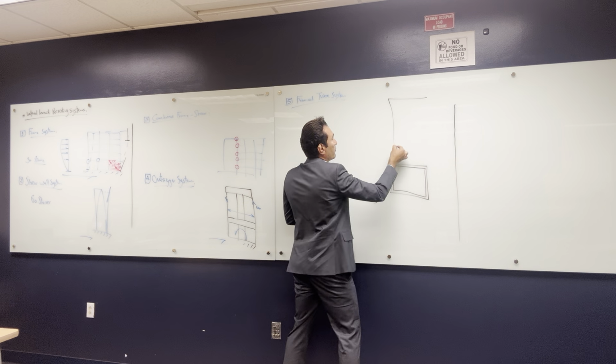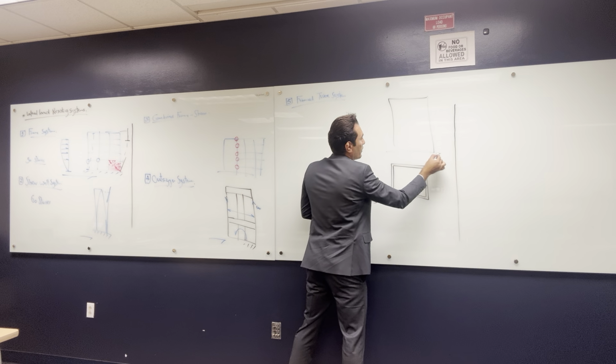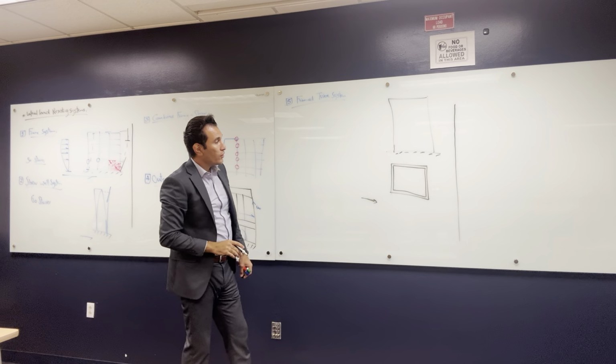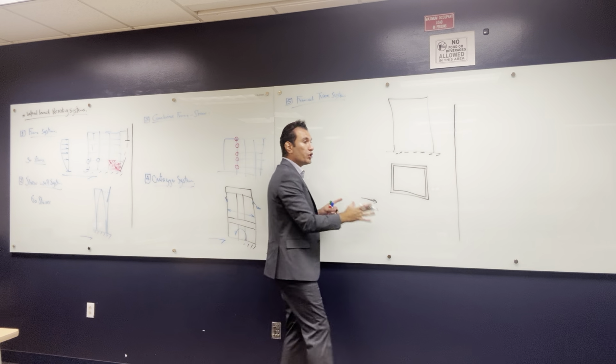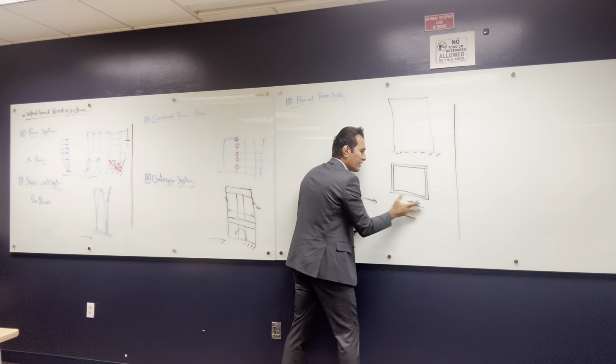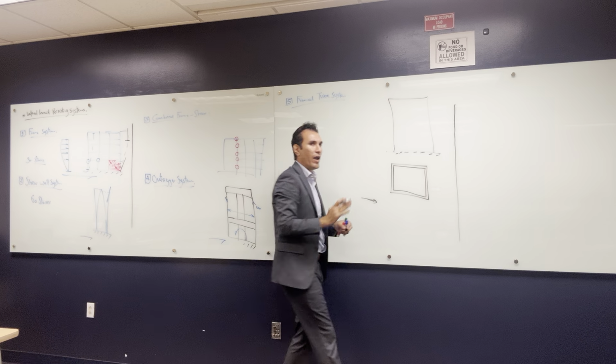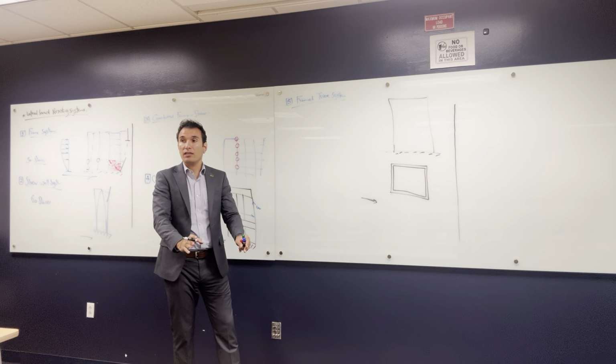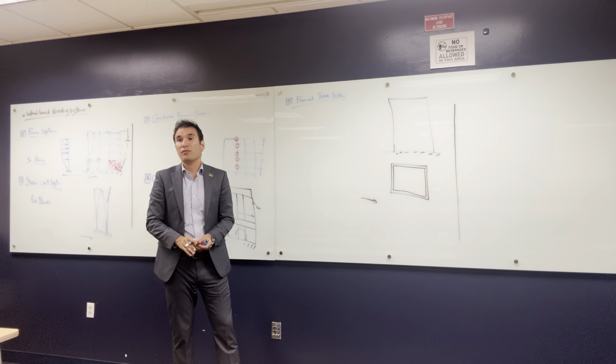The building side view is something like this, and I'm looking from the top. All right, and you have two shear walls, and this shear wall is 60 meter and 60 meters. So you have 120 meter of shear wall length resisting this lateral load. So you are making your building very strong.